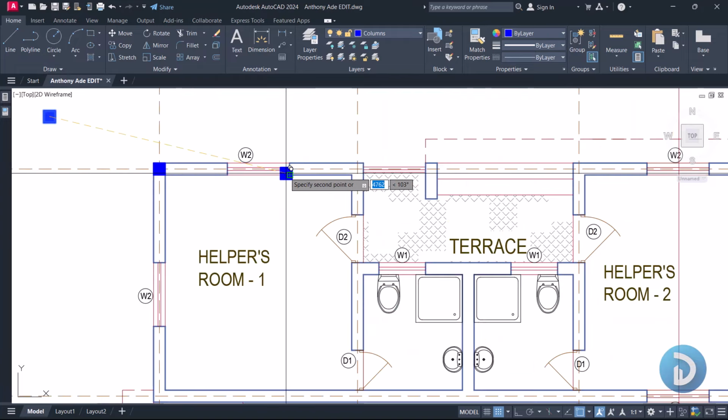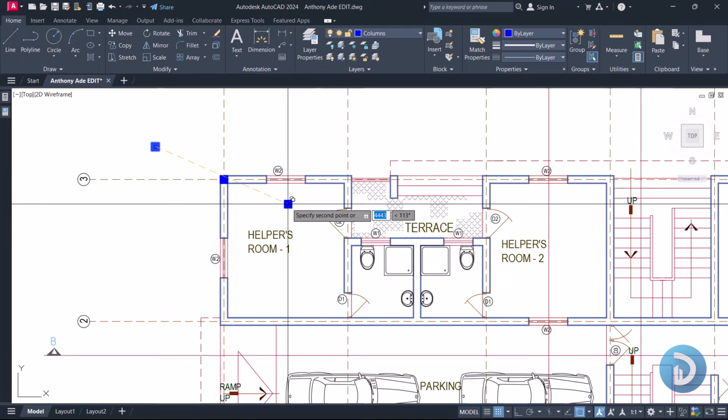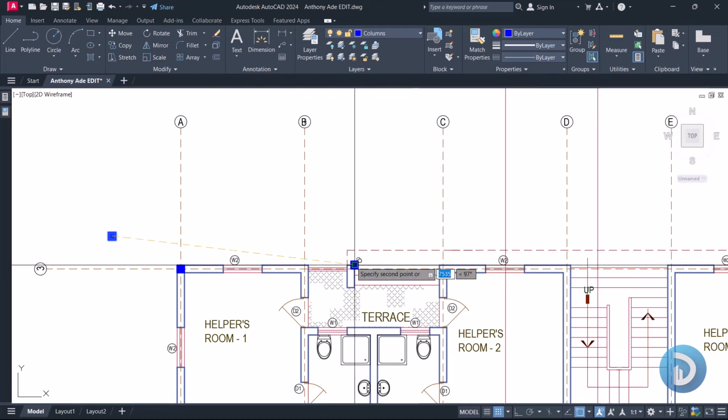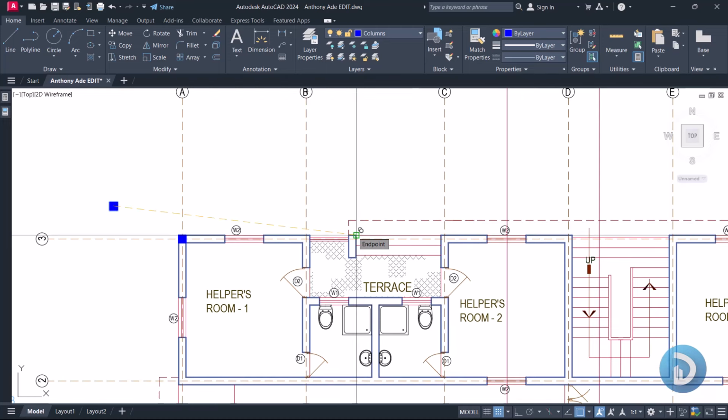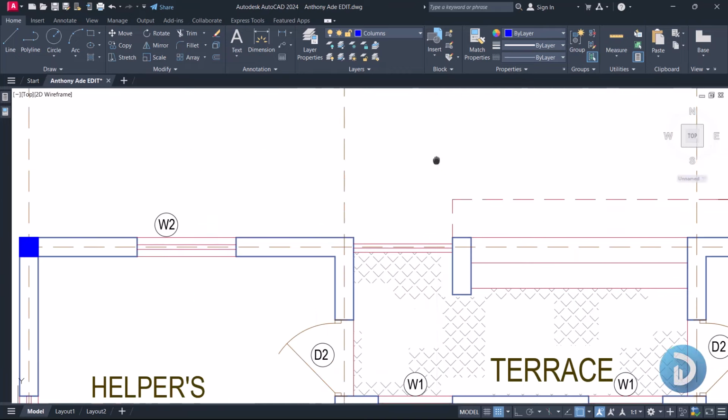If the proposed positions of our column does not have any grid line, then we can go ahead to create our own grid lines. But it is always advisable we start with the grid lines that come with the architectural plan. So while constructing the architectural plan, the grid lines on your architectural plan will be the same as your grid lines on your structural plans, but we can also add our own grid lines in order to suit the requirements of the structure.